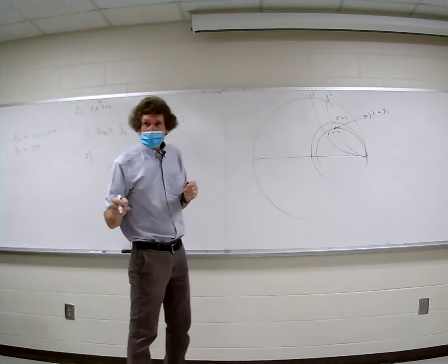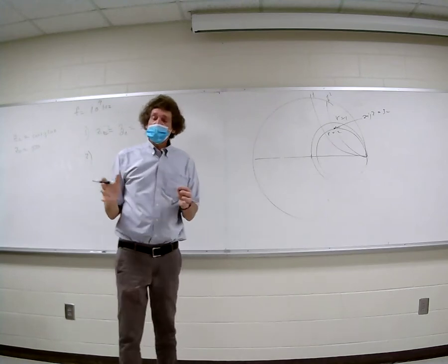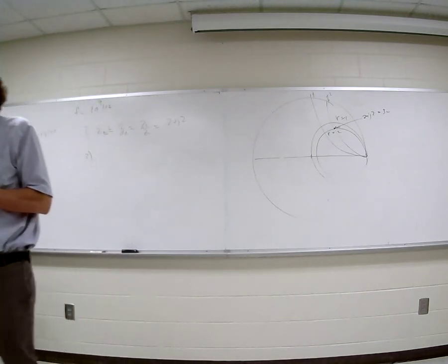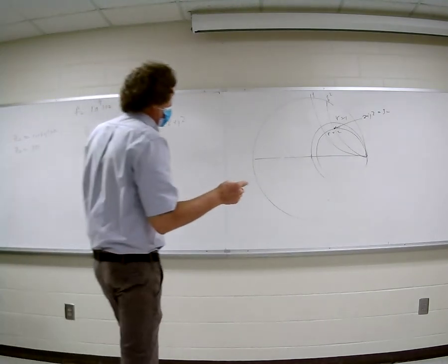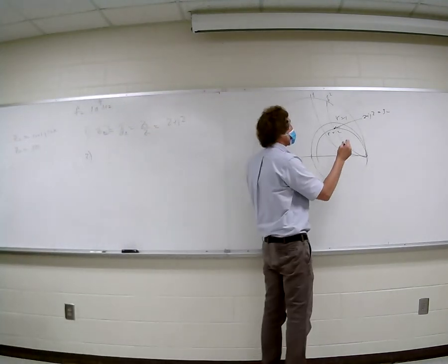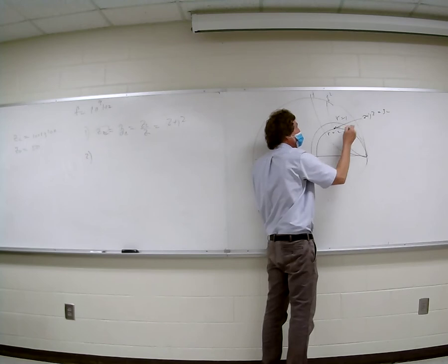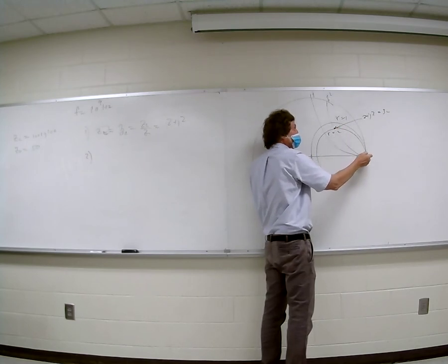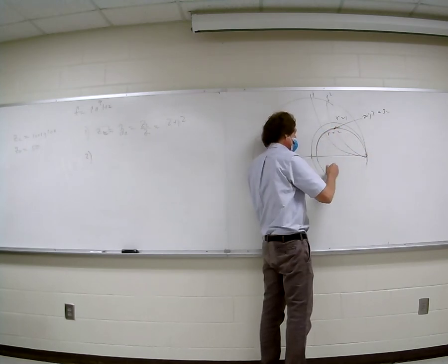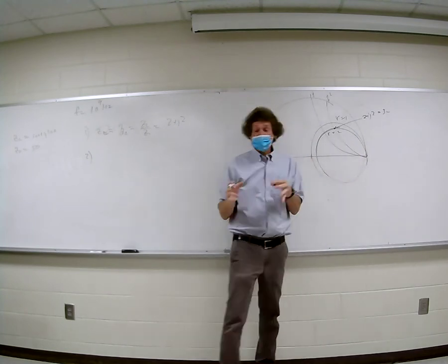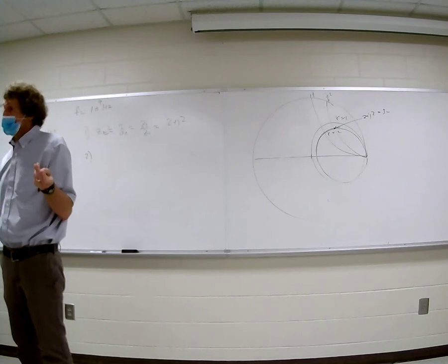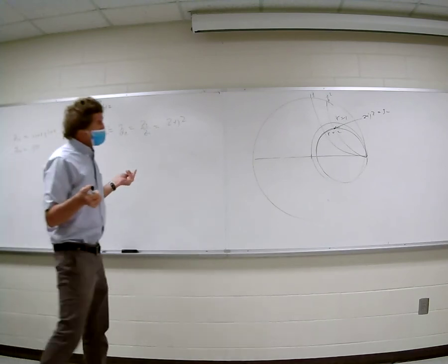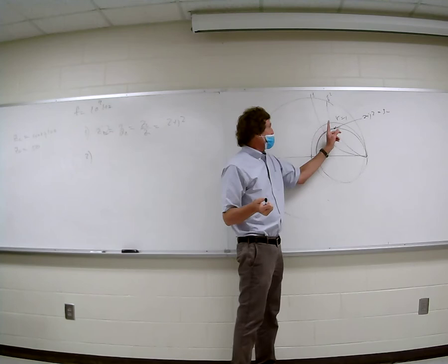Everybody agree? Now hear me. Anytime we're doing impedance matching, the only thing we're going to add is an imaginary reactance. It'll never change the real value. So if you take a look at this trajectory, everywhere I go around this orbit, where r equals 1, I can add or subtract some imaginary component and get rid of the imaginary term, right? I can make it 0, I can make it anything. But the problem is, no matter what I make it, I can't get to the one circle.